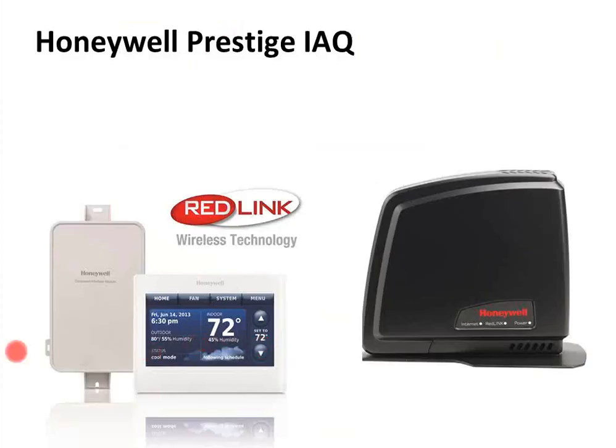Let's see if there's any last questions on that one. And More asks if you have to have a BAS system in place for this thermostat or if it will work without such a system. Yeah, this thermostat is intended for people that are not going to go the BAS route. If you've got a VAV system with 30 VAV boxes and a chiller and a boiler and an air handler, that's going to be a building automation system. But if you've got two or three little rooftop units and you look at a building automation system and say, oh crap, that's going to cost $6,000 and this is going to cost $600 or whatever, that's when you would use this. So these thermostats are used unrelated to a building automation system.